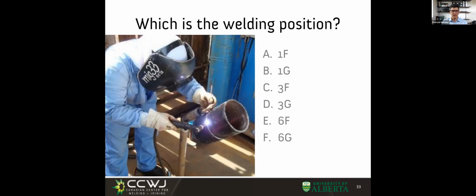That was a question from an exam. It's a welder that is qualifying. There is a European system that I included because it's so easy to remember. They don't call it positions 1, 2, and 3. They call it A for flat, C for horizontal. They have B for the case, for example, of fillet welds, which in the case of AWS is ambiguous.